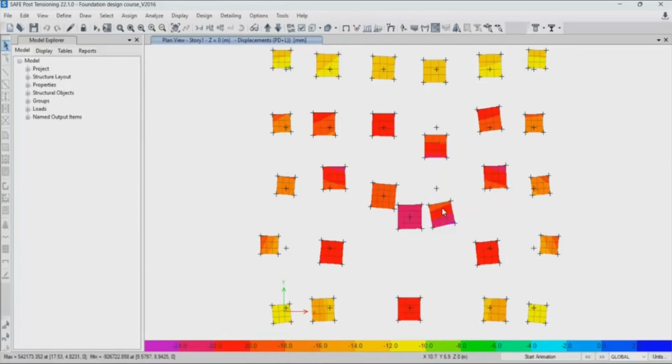Or the second way, what you can do is introduce a ground tie beam, or what we call a strap footing. If you have a couple of columns that refuse to stabilize, they keep failing the differential settlement check, you can structurally tie them together.